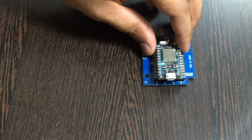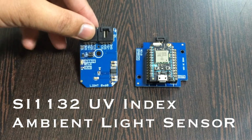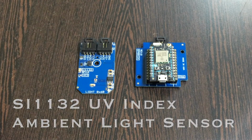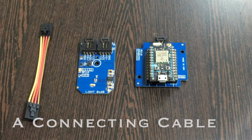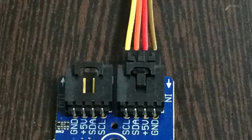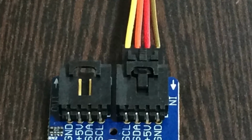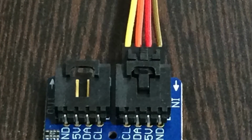The next part is to have a look over the sensor that is UV index ambient light sensor SI1132, and this here is a connecting cable. Now make the connection of the cable and the sensor, and make sure that the brown wire of the cable should be connected to the ground terminal of the sensor, and same goes for the I2C Shield.